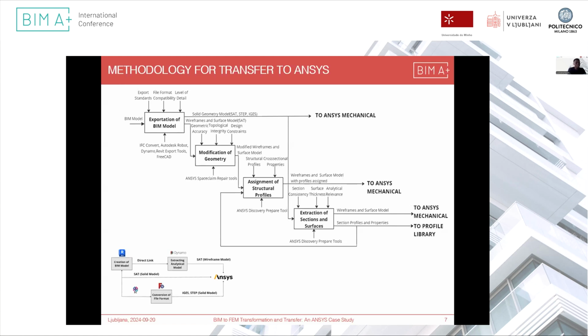Upon importing the model into ANSYS, ANSYS has software programs called ANSYS SpaceClaim and ANSYS Discovery. And these tools are used to really repair the model. And repairing the model includes assigning material, assigning section profiles to lines, and also checking whether there are any gaps in the model.